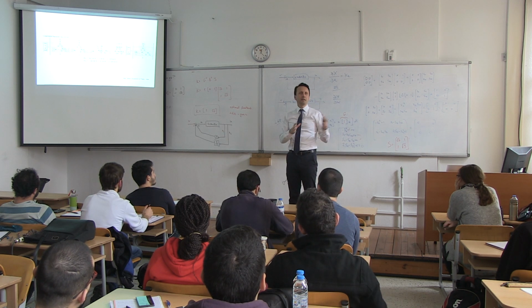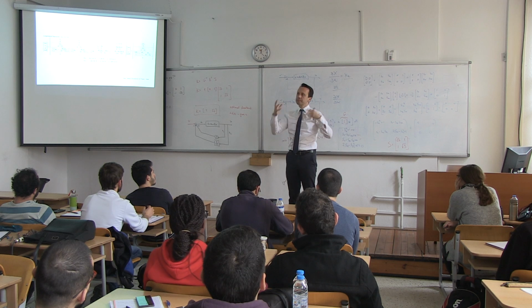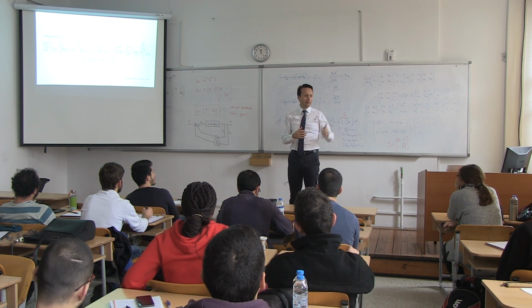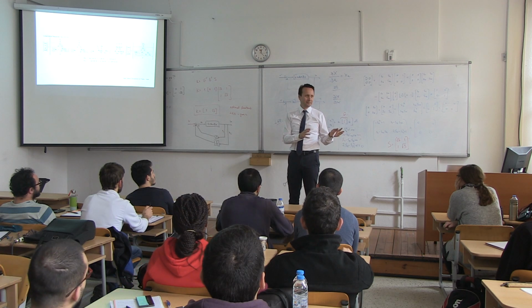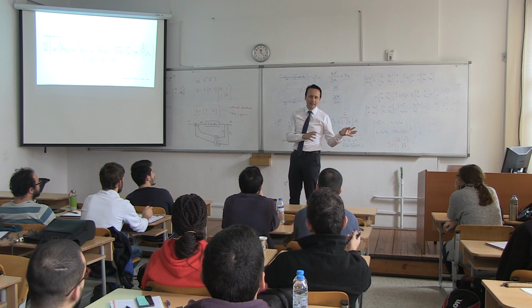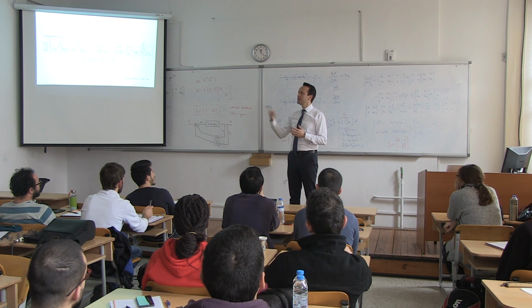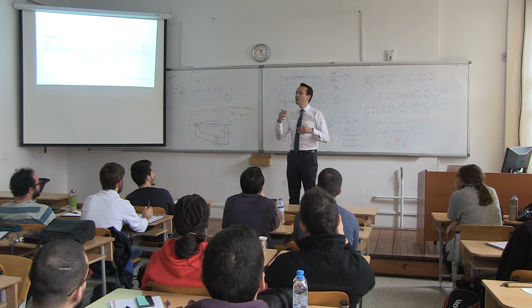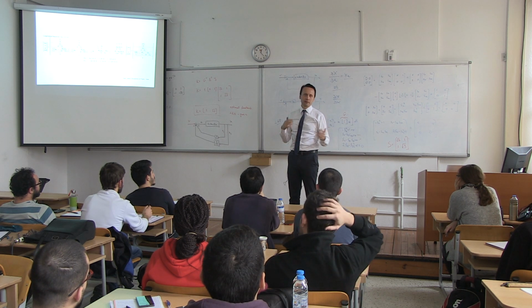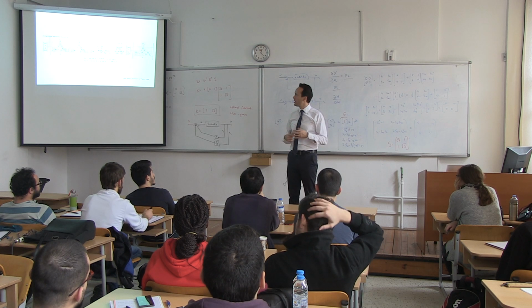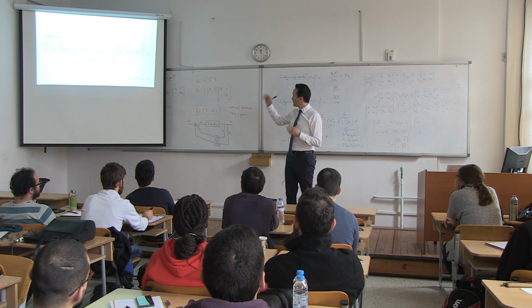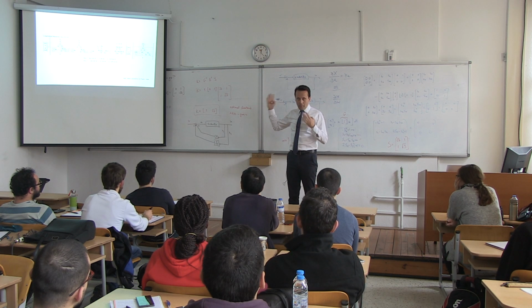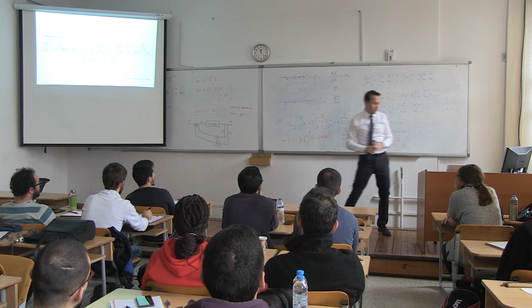Okay? When you have an aircraft that already flies, that is one way. But oftentimes when you design an airplane, you haven't flown it yet, and you still need those numbers. And then all these estimations and testing and all that stuff becomes quite important. So I just wanted to remind you that you still need the aerodynamic derivatives, mass and inertia terms in order to calculate the A and B matrices.